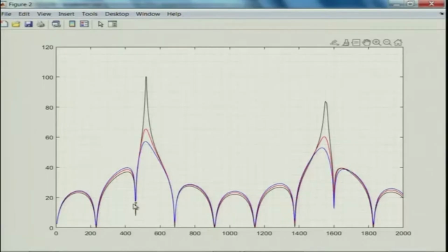So 15% porosity, 20% porosity is still a very highly porous section, but typically if you have 30% or more porosity, it is almost acoustically transparent, but in the process your perforate impedance expression tends to become problematic, because you have your zeta. Zeta is dependent upon porosity in the denominator. So you might end up with exponentially large numbers when you use the function EXPM. It goes beyond the machine precision and fails there.